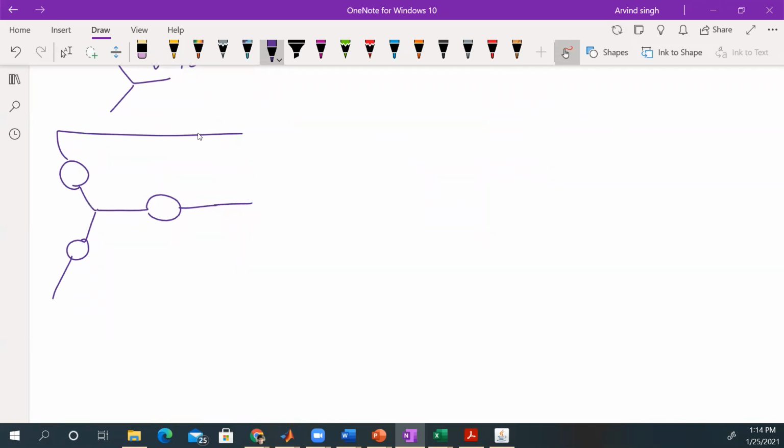Right, we have the I phase here, I line, and then across here is V phase, and here we have V line to line. Now notice we say I line and V line to line. That is because the I line is the current through the line, and voltage line to line is because it is the voltage between lines. So it is not line to line current, it is just line current. And it is line to line voltage.